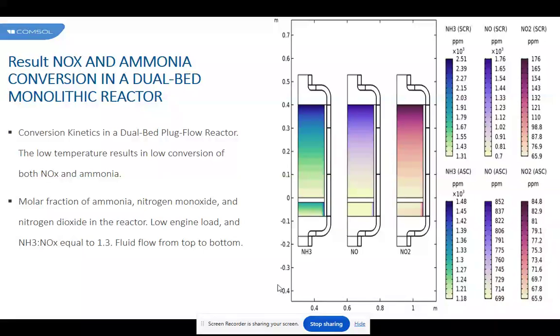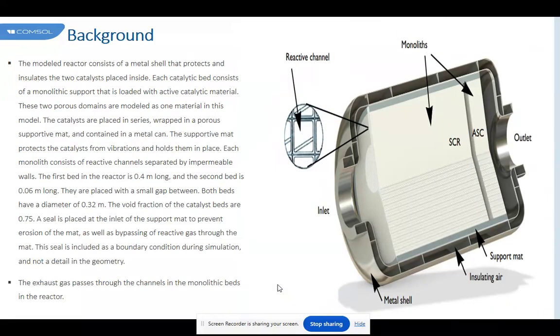The domain tested was a catalytic converter similar to those tested in experimental rigs. That is an inlet pipe, in this case 1000 millimeter long and 27 millimeter in diameter, followed by a 67 millimeter long diffuser connecting the pipe with a monolith 152 millimeter long and 60 millimeter in diameter.